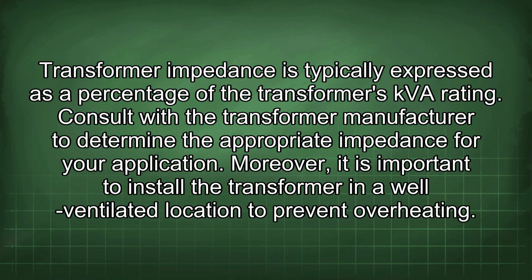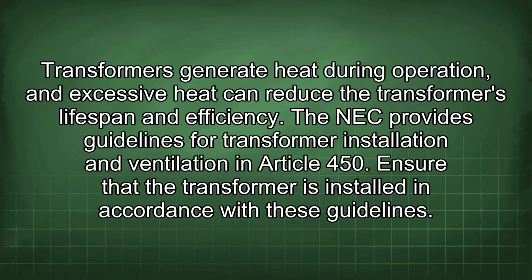Moreover, it is important to install the transformer in a well-ventilated location to prevent overheating. Transformers generate heat during operation, and excessive heat can reduce the transformer's lifespan and efficiency. The NEC provides guidelines for transformer installation and ventilation in Article 450. Ensure that the transformer is installed in accordance with these guidelines.